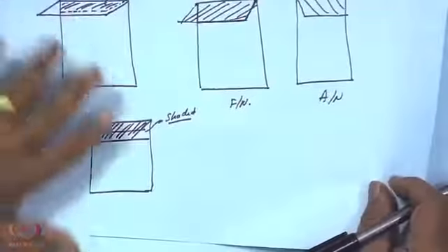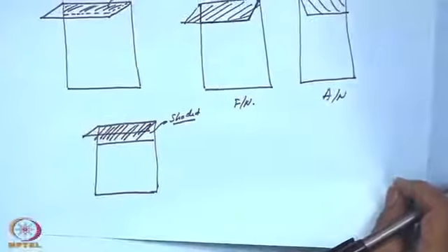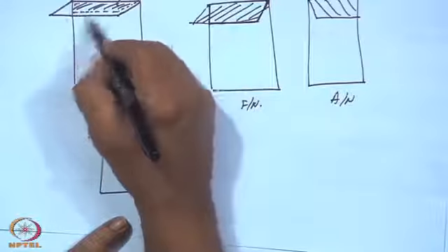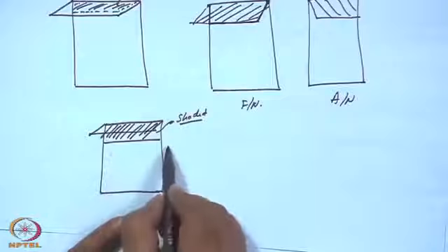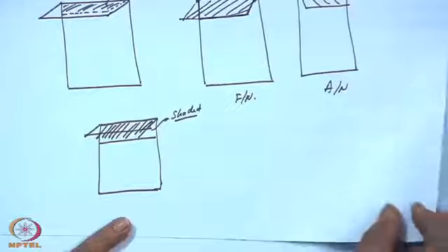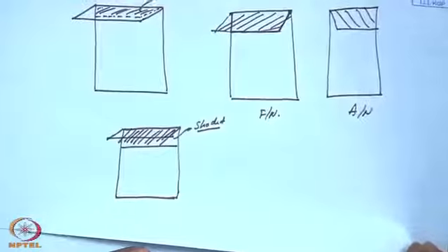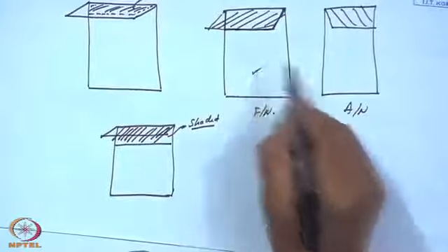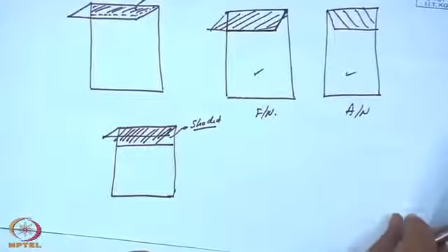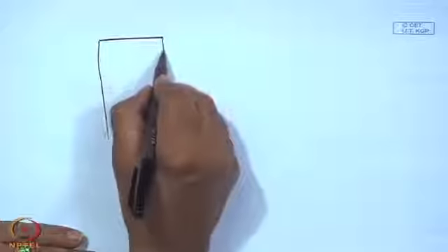And if it is equal to the width of the window, then I can have a situation like this, where a sort of trapezium is shaded, and a complete rectangle could be shaded if it is exactly facing the south or facing the sun, or it could be a degenerate case like the ones I have shown here or here, depending upon whether it is forenoon or the afternoon. And you can have still further degenerate cases.